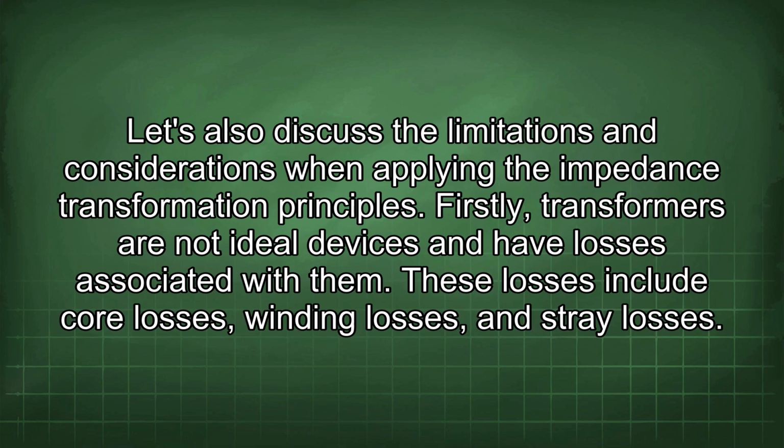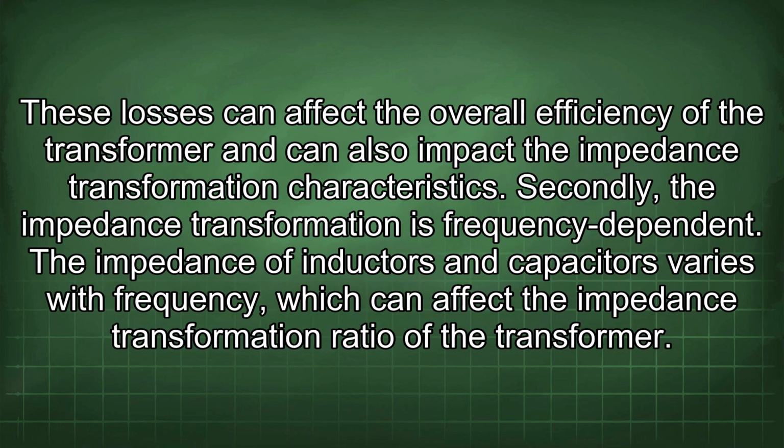Let's also discuss the limitations and considerations when applying the impedance transformation principles. Firstly, transformers are not ideal devices and have losses associated with them. These losses include core losses, winding losses, and stray losses. These losses can affect the overall efficiency of the transformer and can also impact the impedance transformation characteristics. Secondly, the impedance transformation is frequency dependent. The impedance of inductors and capacitors varies with frequency, which can affect the impedance transformation ratio of the transformer.